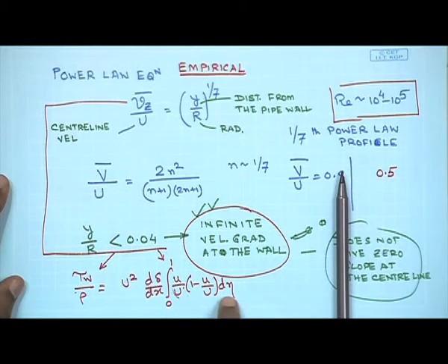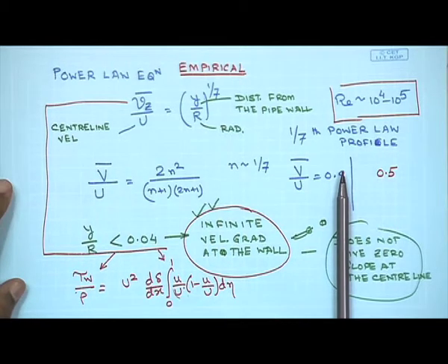So, whenever you integrate an expression that contains some experimental error, the error gets minimized, the error gets reduced. But what happens in tau w? In tau w, you have to express tau w in terms of velocity gradient. That means you are differentiating the velocity profile. The moment you differentiate data containing error, you magnify the error.